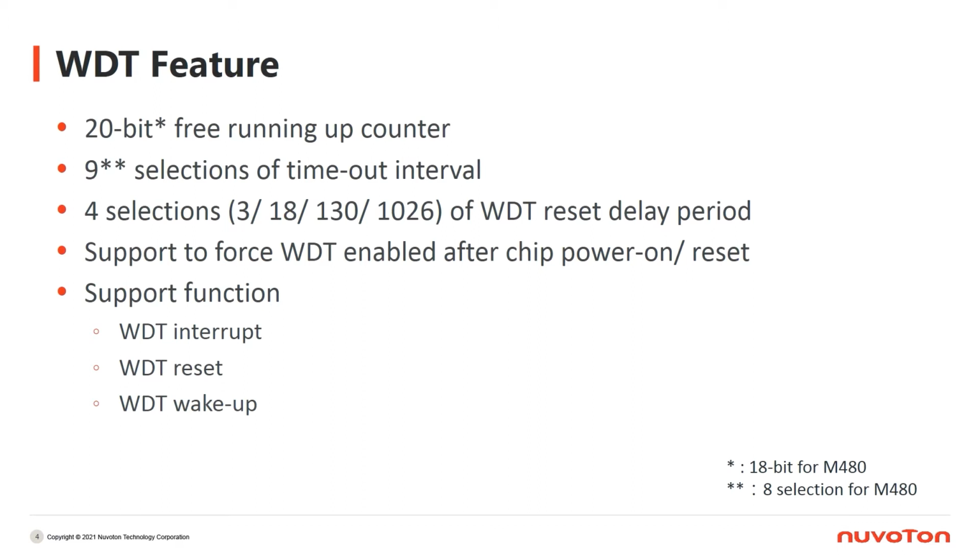Before resetting the system, you could add a delay period. The delay period will give system some time preparing for the reset. For example, to store some data before resetting system. Therefore, we also provide 4 selections of WDT reset delay period for user to choose. In addition, we support to force WDT enabled after chip power on or reset.